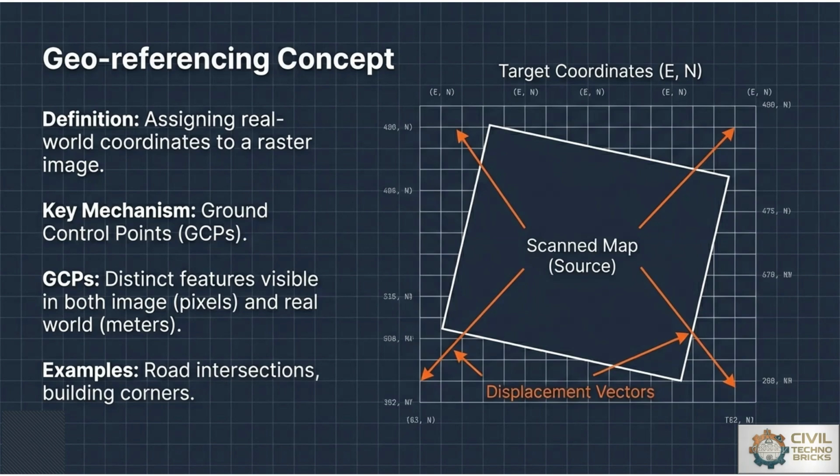The accuracy depends on control points and transformation methods, which is the most important characteristic. In civil engineering, it is used in land records departments, mapping and zoning in town planning, and overlay analysis of various layers, which enables the integration of multiple data sets in GIS by using the georeferencing concept. So we have to superimpose any satellite image or raster image on the existing topo sheet. With respect to that, we can check the displacement and the mechanism, which is based on the ground control points.